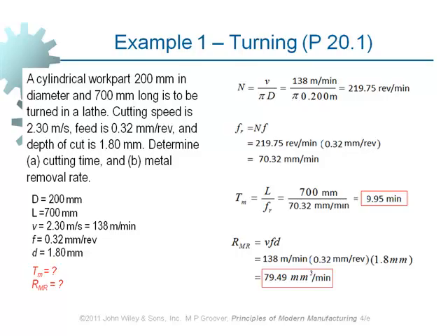So, in practice, we've got to see what spindle speeds we've got available, which is close to this, and take that one into consideration. You've got 200. Okay, now substitute 200 in your problem and continue with it. Which gives you a different cutting speed from what you are using.